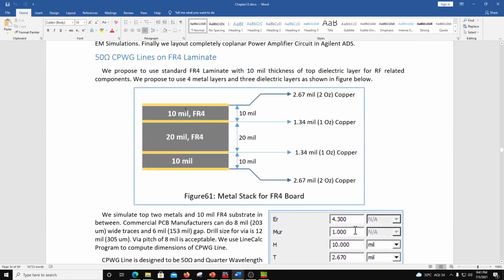So this is the profile of a board, right? So remember I told you that Momentum is used for planar circuits, and PCBs can be done, but then this is not a cross section, it's a profile. So the extent on left and right of this doesn't make any meaning. It's not a cross section of that board, it is a profile. So there is no meaning to going from left to right.